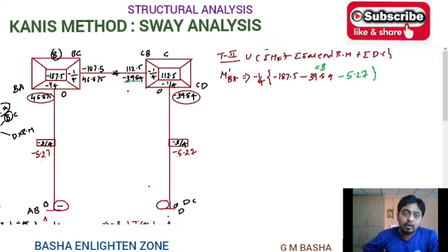If you go for third trial, you will get second trial displacement contribution. If you go for fourth trial, you will get a third trial displacement contribution. Like for each and every time, for first trial only you will get zeros initially. So the remaining times, you will get previous trials' displacement contributions and displacement moments. So if you simplify this one, you will get how much the value will be. It will be around 58.15 in kilonewton meter. So write down immediately here 58.15.